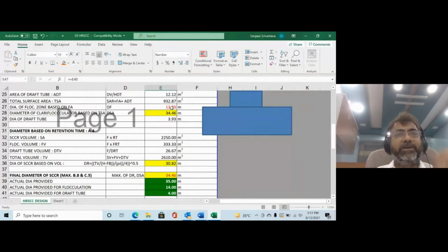Now he will say, sir, this is a typical design of a clarifier. Here you do not require one flocculator. So you decide whether I will put 2 paddles of flocculator, one at each side, or I will put 4 paddles of flocculators in that zone, because it cannot come in the center. Now this is where the design becomes tricky, and we always consult the agitator manufacturing company, giving them our design and also the sketch of our clarifier, and then seek their suggestions on whether 2 flocculator paddles are enough or you require 4 flocculation paddles.